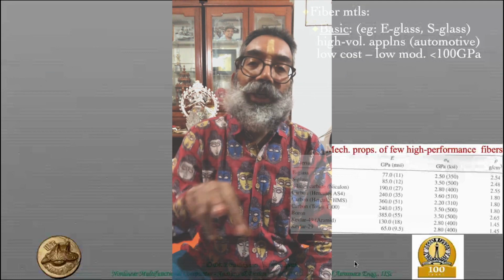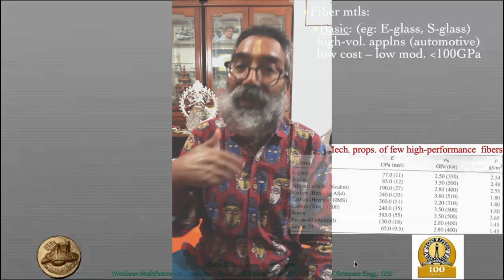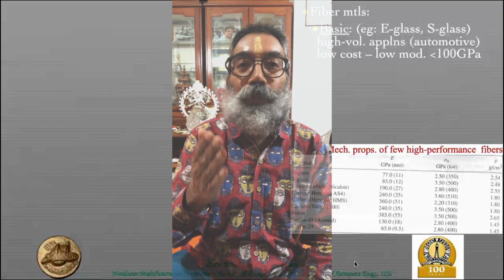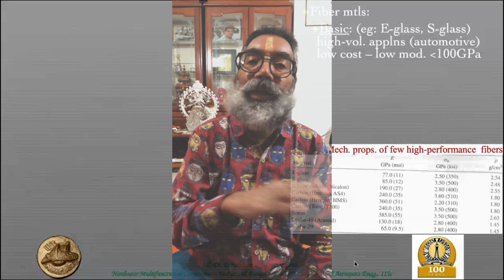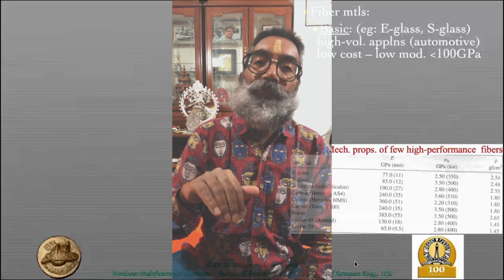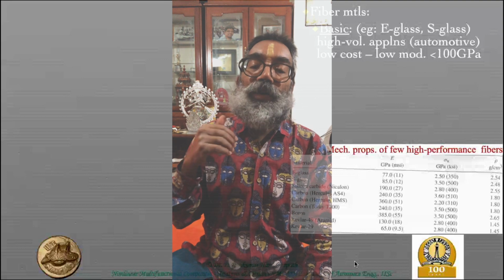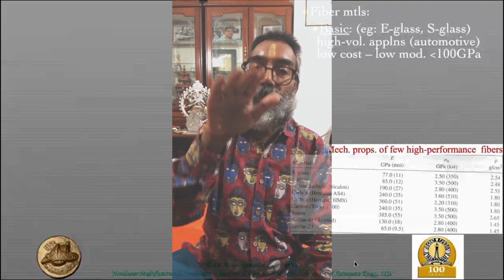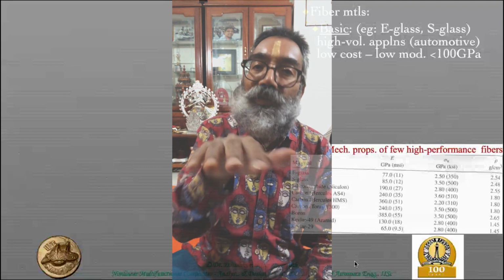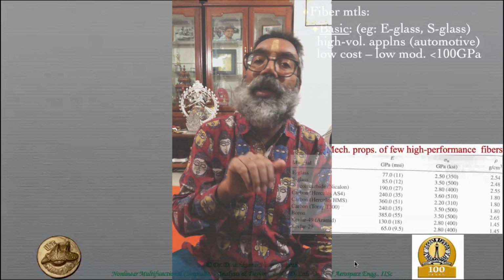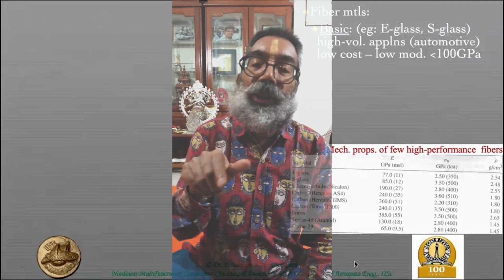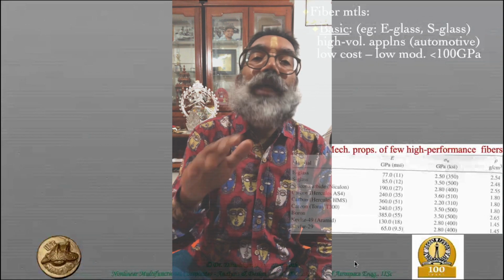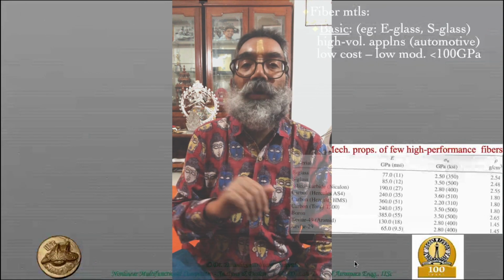The other complication that you brought about is in terms of the multi-axial loading. Very good point again, because you're designing not only for loads in a particular direction, but in multiple directions. But a priori, we know which are the dominant directions. So we tend to have more layers of fibers along the direction in which the load is. Even in a multi-loaded situation, the loads in all the directions are not going to be of the same magnitudes.